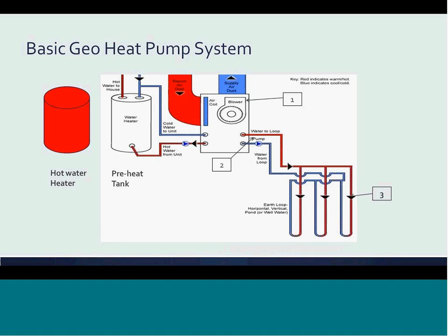Important to note here that for geo heat pump system designs, a balance between heating and cooling is needed to minimize ground loop size and cost. A lot of calls from central plant owners who believe that the best way to utilize this new technology is to remove their cooling towers and just put in a ground loop. Well, that's fine, but we must also have a way to use the heat rejected at a later time, either stored in the earth for heating in the winter or immediately in an energy recovery type application such as domestic hot water, which is typically a year-round load.